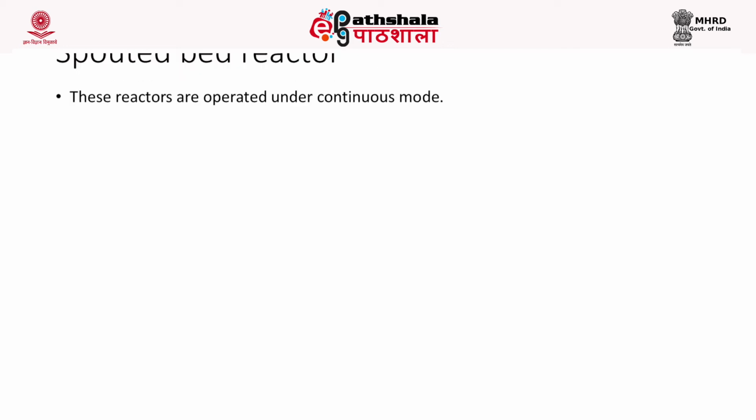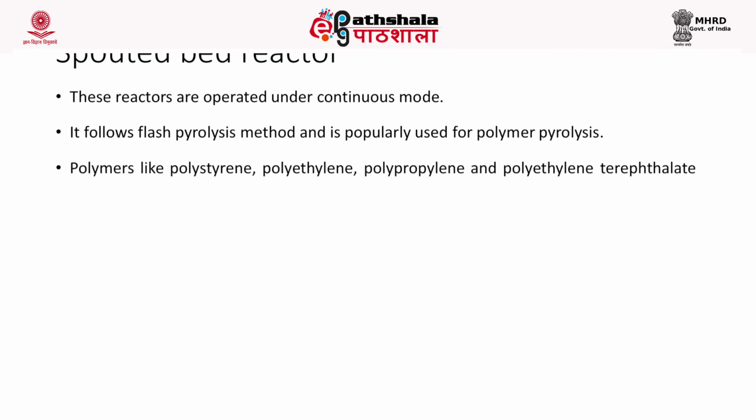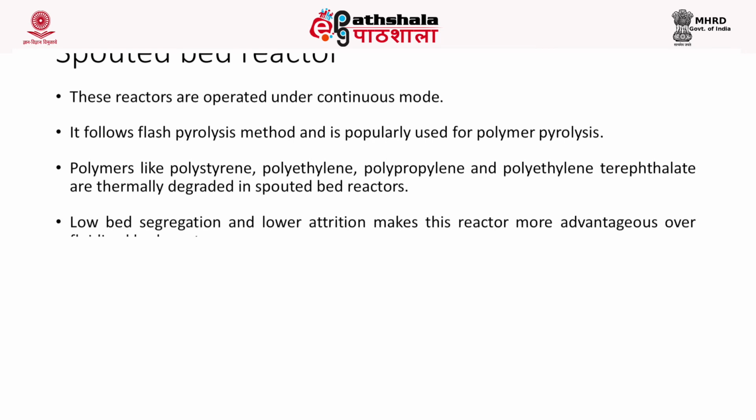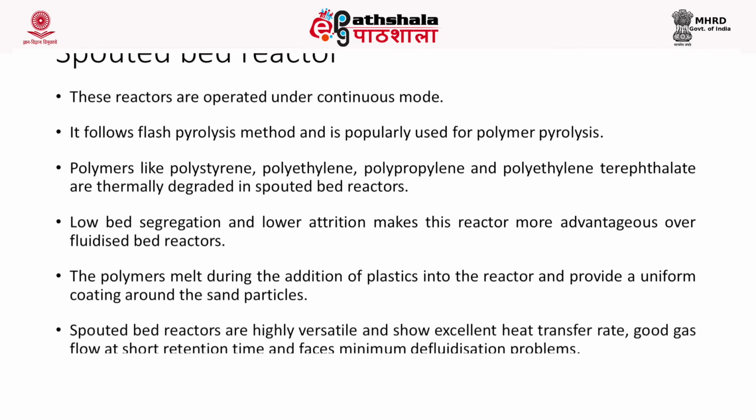Next type is a spouted bed reactor. These reactors are generally operated in a continuous mode. It follows a flash pyrolysis method and it is used again for the polymer pyrolysis. Polymers like polystyrene, polyethylene, polypropylene, polyethylene terephthalate, that is PET bottles, all these things are thermally degraded in spouted bed reactors.